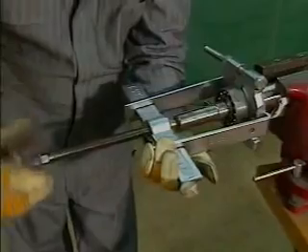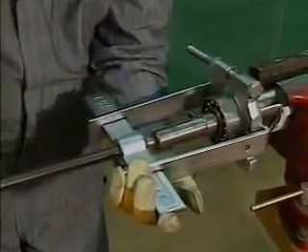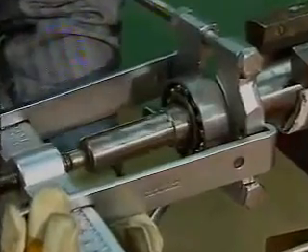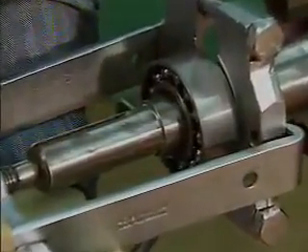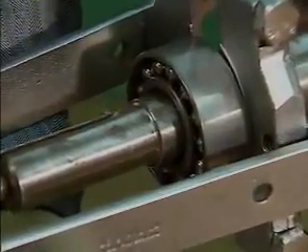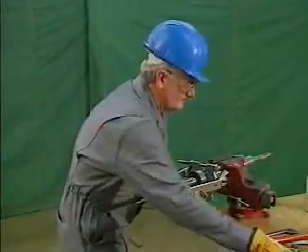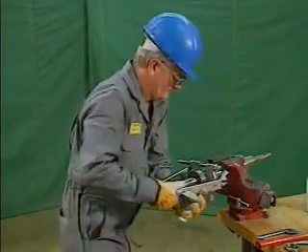After a bearing has been removed from a shaft, it should be handled carefully. It should not be left where it will get dirtier, and it should not be rotated, banged around, or dropped. Handling the bearing carelessly will only make the task of determining why it failed more difficult.